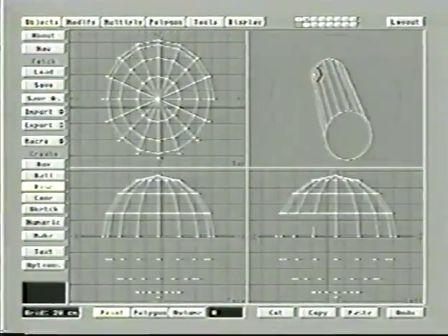Now, the way the Boolean features work is they do operations between the 2 different layers. They either add, subtract, or in some way combine the 2 layers. Now, the layer that is our active layer, our foreground layer, is the main one. The one that's the inactive layer, and we're going to do a subtract here at first, is what's going to be subtracted or pulled out from our active layer. So let's switch our layers up using the quote key.